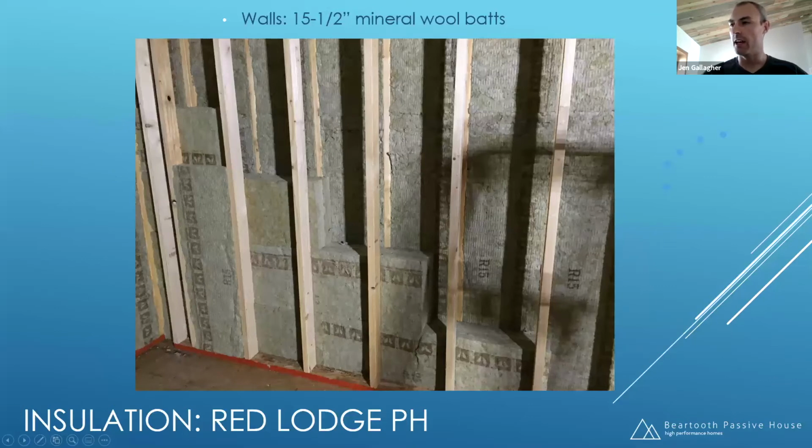And then you saw back when we talked about air tightness, that Intello material went over the inside of this wall. Then what we ended up doing is also forming another 2.5-inch cavity that was also insulated before we actually put on sheetrock. So that got us to 15.5 inches thick of wall cavity.